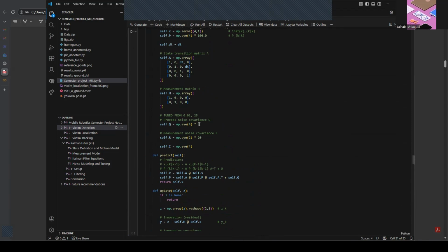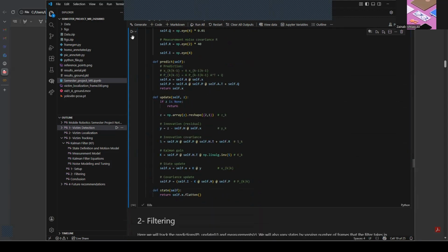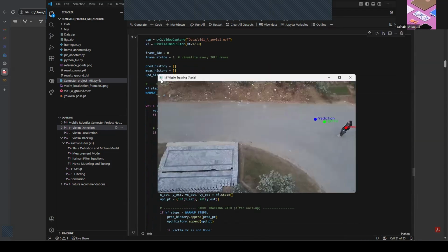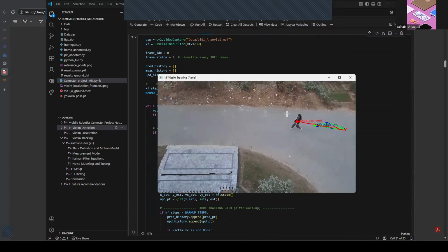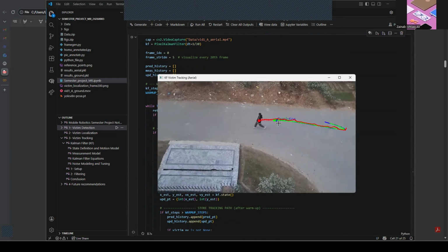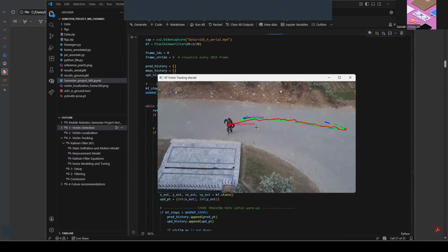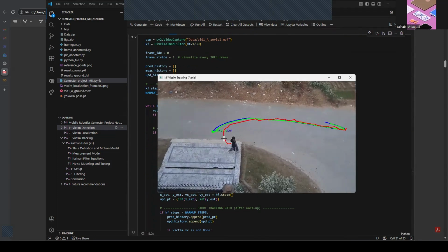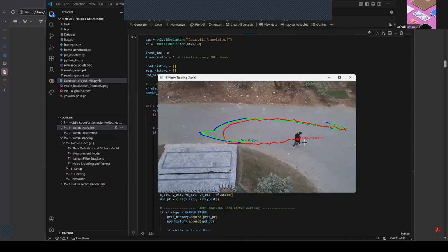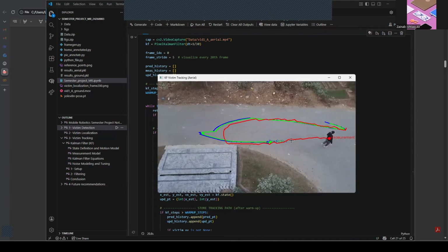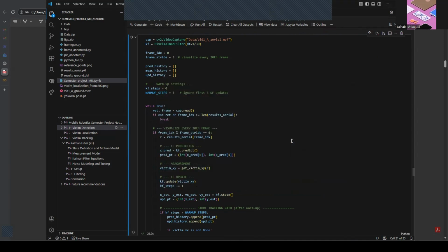So here I have my Q and R. Let me try giving Q a very small value, and let me try giving R a very large value, maybe 40. Let me run my function again for Kalman filter and run my filtering again. So it works pretty slowly, and there you go, it deviates again. So you can see it's way far behind, which just shows that we gave it a way bigger noise covariance.